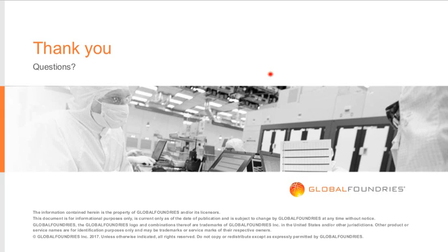But you can see that we have already shown different kinds of circuit design and shown the model hardware correlation, and it looks good either from the switch or from the PA point of view, for small signal and large signal. So it shows reasonable model hardware correlation. So basically this PDK is already ready for the design activity. Great, and that's an important point to make, that both analog and digital can be done on the same chip. Yes.